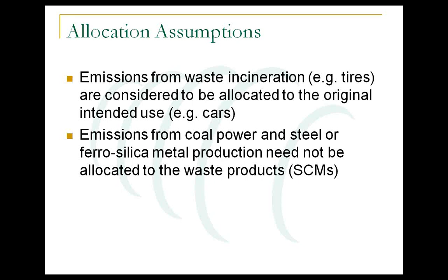Similarly with supplementary cementing materials, this is really important. So, for example, emissions from coal power or from steel manufacturing don't have to be included when you're including things like fly ash and slag in concrete. Now, again, if there's some processing involved, in some cases there's some beneficiation for fly ash that would require some processing, yes, certainly you would include that. Or slag cement, same thing. Usually there's some processing involved. Well, not usually, always there's processing involved. You have to include those impacts, but not the impacts of the original manufacturing process for steel or for electric power, for example.